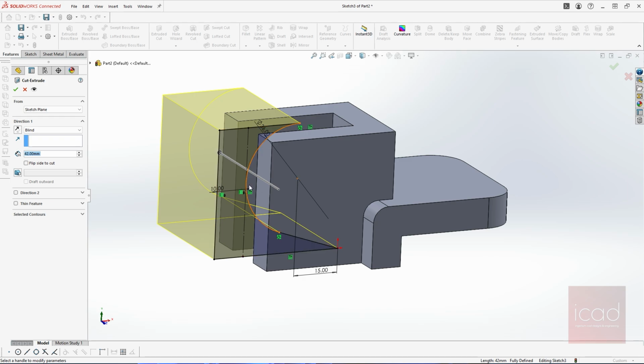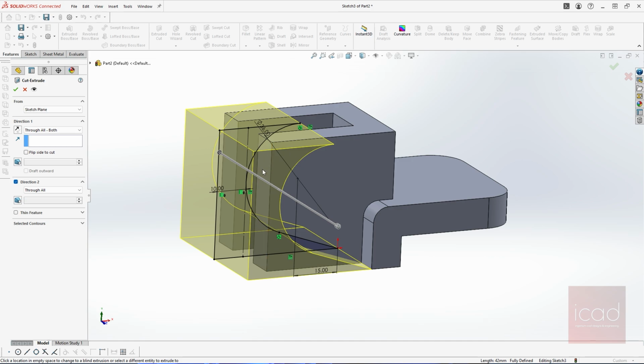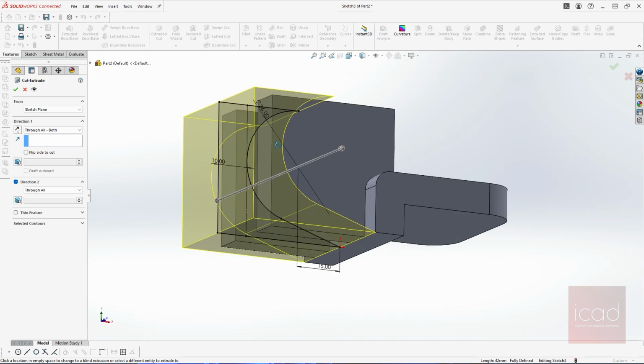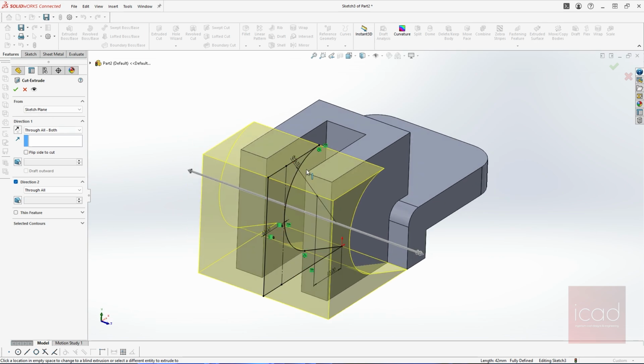The error was, since it was tangential, I don't think it could take that precisely. I mean the two contours, so that's why it must have been giving an error. And now we have given the offset. There is no tangential coincidence between the line and the curve, and it's a single contour. Now that's it.